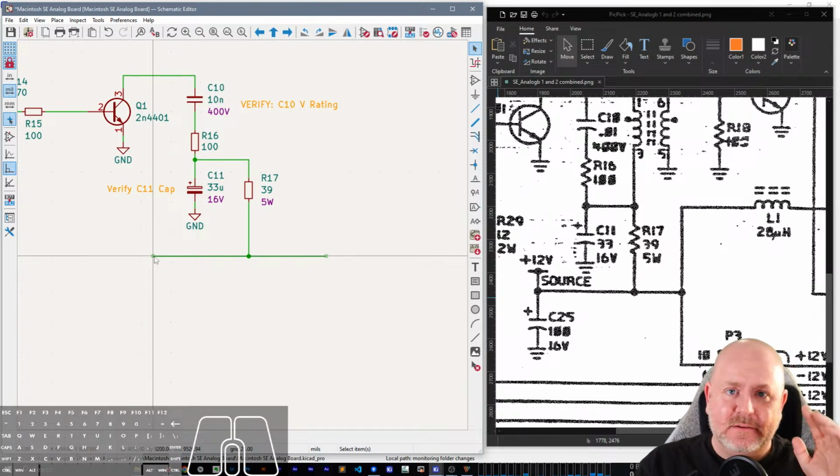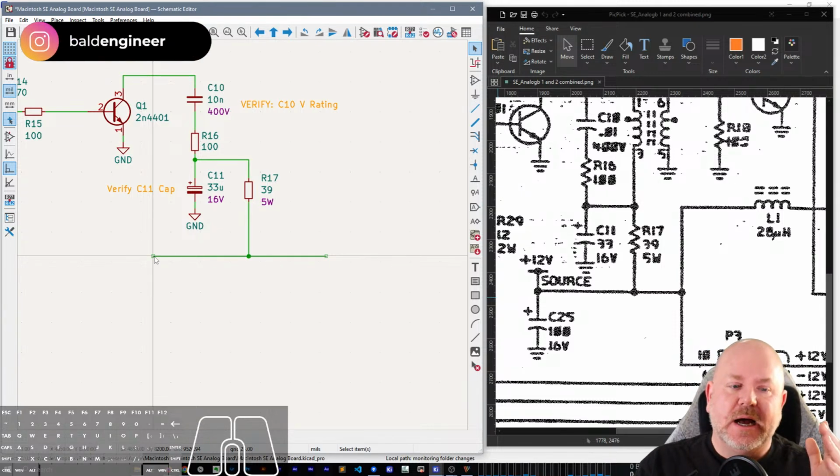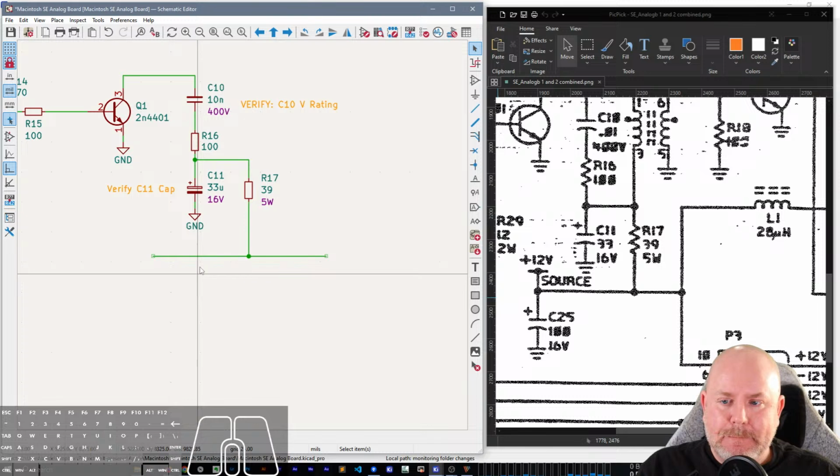By the way, on the LED thing, I sincerely mean this: always check your LED with a DMM. Put it into diode mode. It probably won't be able to measure the forward voltage, but it will at least light up the LED in the correct orientation. Always check with a DMM.